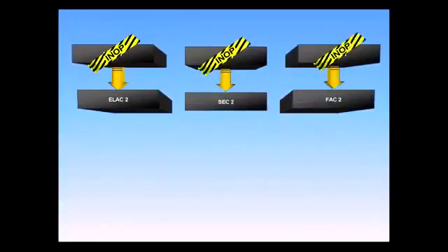In case of a computer failure, the second computer of the same type takes over, ELAC, SEC, and FAC cases. Note that SEC3 is only used for spoiler control and does not participate, as do SEC1 and 2, in the flight control system reconfiguration.